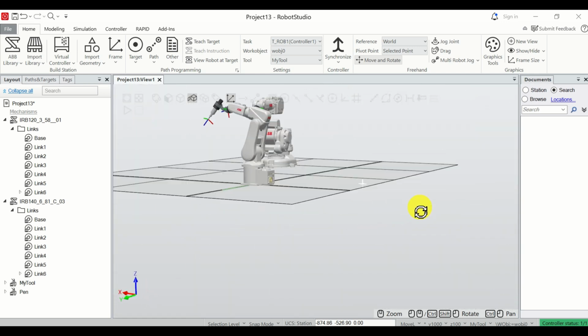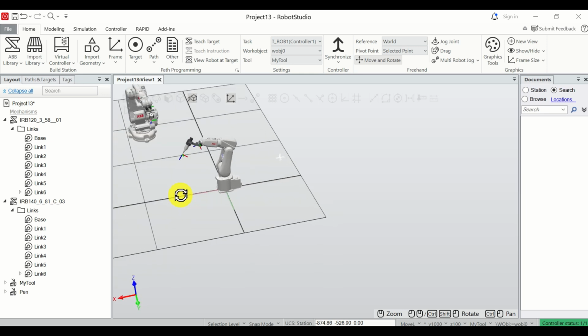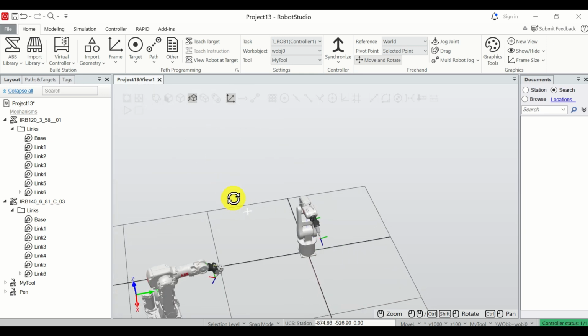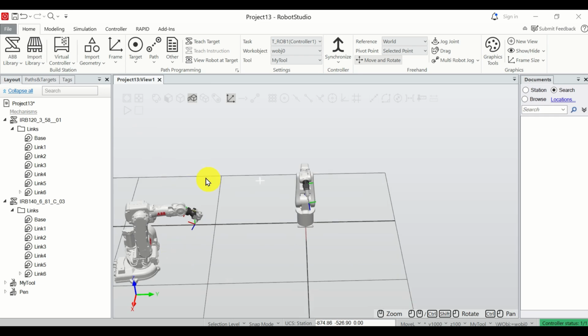The next step is to actually visualize the envelope. This is very important. Envelope represents the limits of robot motions. And by visualizing the envelope, we can actually see the limits of motion of our robot, and envelope is also very useful for properly placing some external objects in the robot workspace. So let's see how to see.